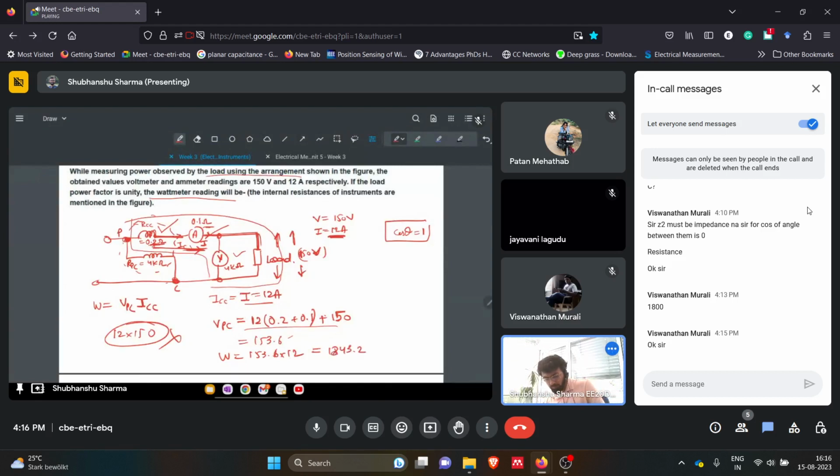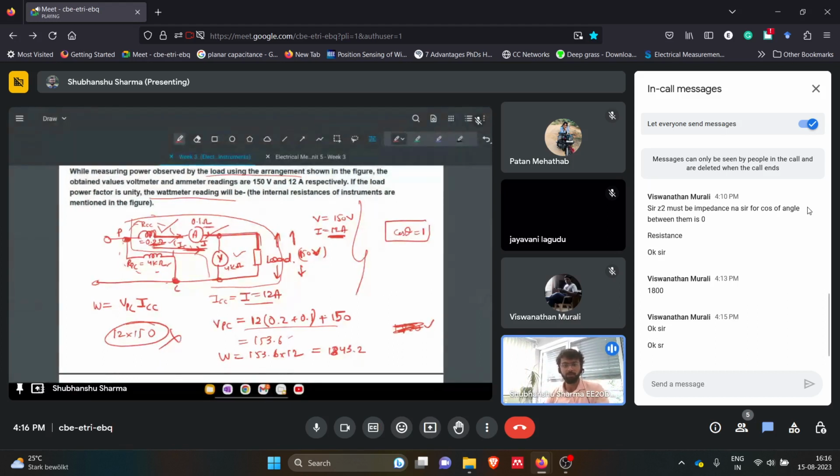So that will be 1843.2. Now when you are solving wattmeter questions, you cannot say, okay, if I have an answer near that, it is correct. You should have the same answer. You cannot say that if it is 1820 then it is correct. No, because these have small values of resistances, but still they make an impact, and the person who is making that question will expect that exact answer from you.